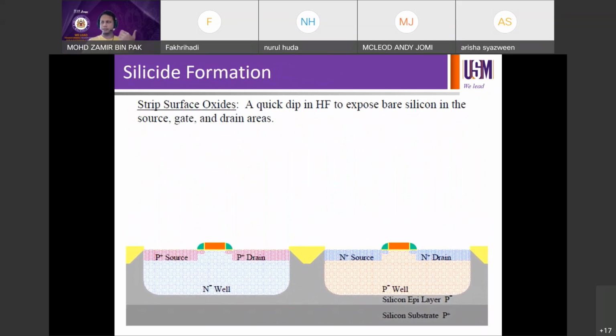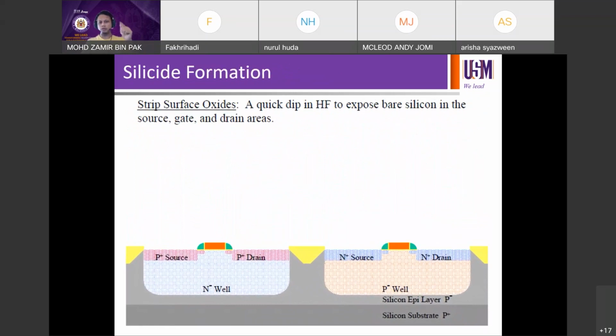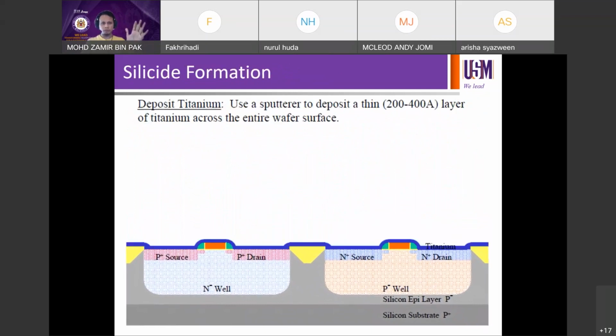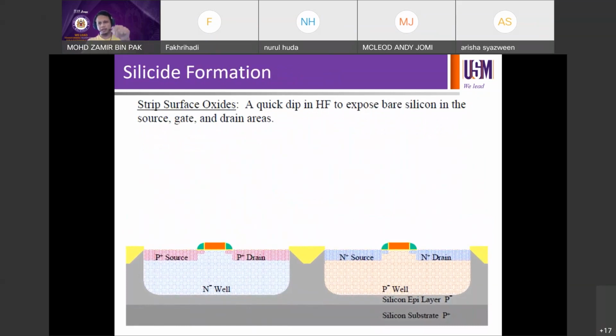So if you go on to an internship or a job as a test engineer, for example, for a wafer fab, you're going to be testing first the moment you finish your gate formation. So the moment you finish your gate, you will be testing at this level. This will be your first test level before you start with your interconnect.